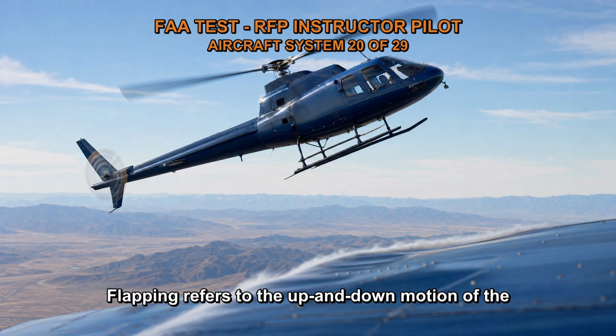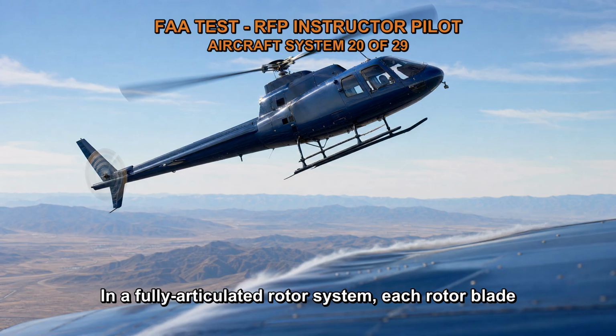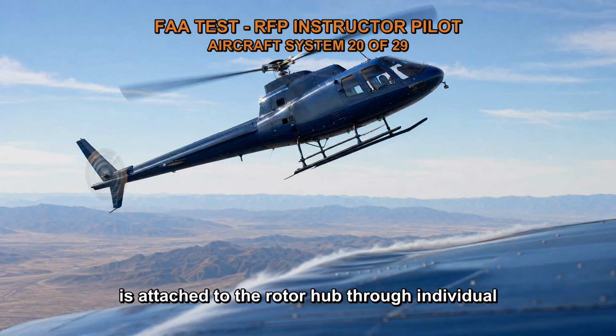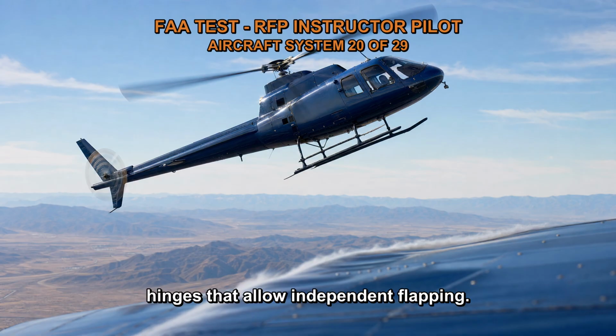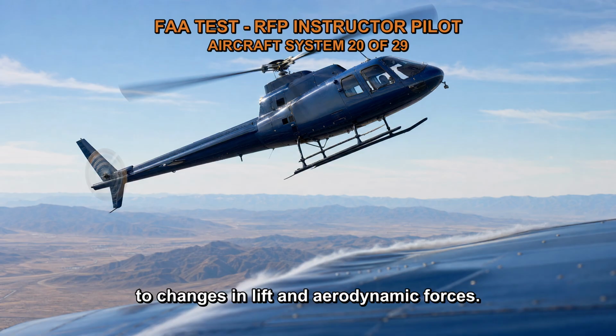Flapping. Flapping refers to the up and down motion of the rotor blades as they rotate. In a fully articulated rotor system, each rotor blade is attached to the rotor hub through individual hinges that allow independent flapping. This means that each blade can move up and down relative to the rotor hub, adapting to changes in lift and aerodynamic forces.